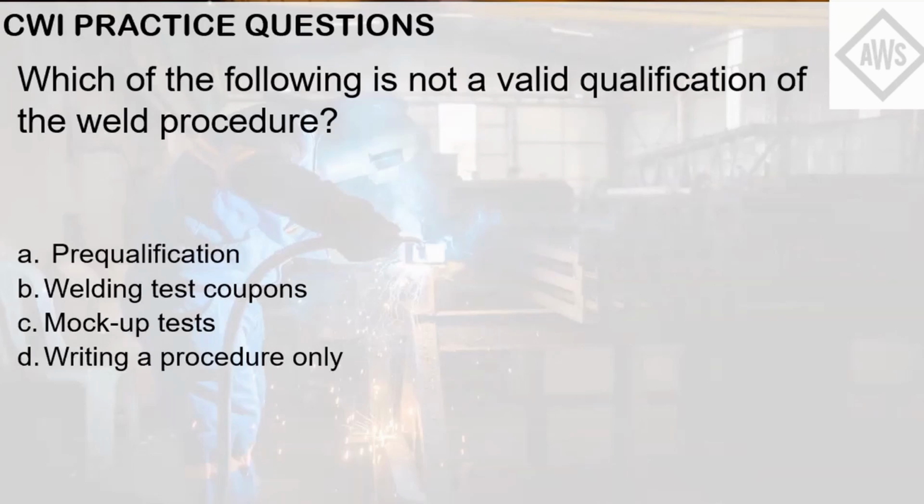So letter D, writing a procedure only. Depending on the code or standard, if you write a procedure only without qualification tests, the keyword here is only, so that is not a valid qualification of the welding procedure. Just a tip, if you are answering a certification exam, over-encompassing statements like only, all, maybe denote a wrong answer.